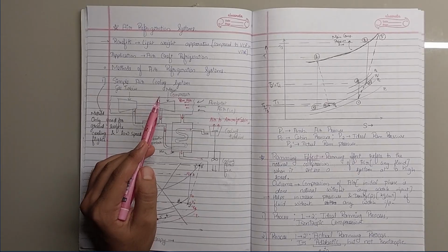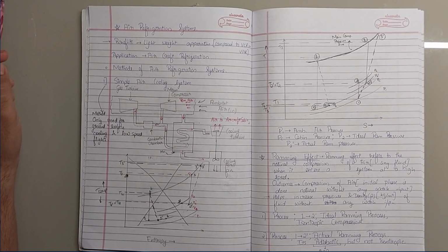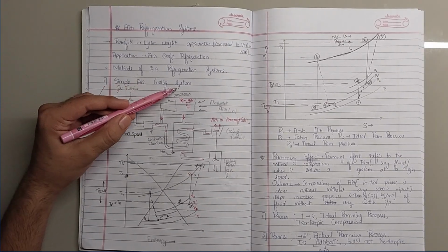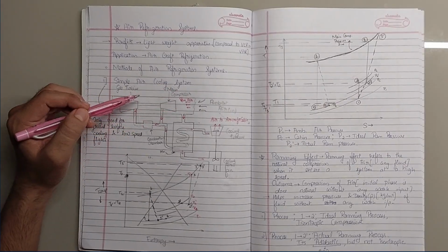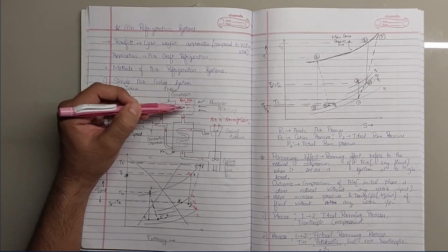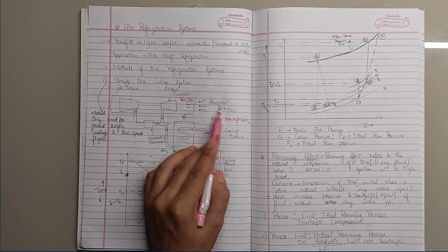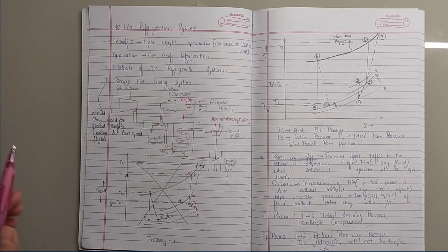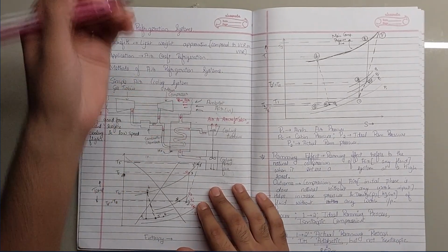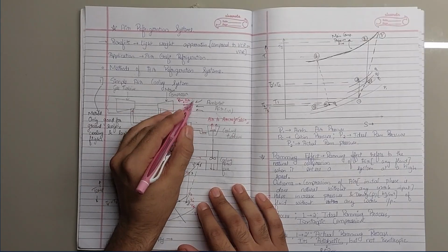An airplane flying at approximately 35,000 feet will always have very low pressure air. We need to first compress it to a high pressure. But using an auxiliary compressor will increase the work done and will eventually decrease the COP. Hence, we have small openings in the aircraft wings wherein the atmospheric air rushes in. An aircraft on average flies at some 800 kilometers per hour, and the air moving opposite to it is at the very same speed, so it will pass through and undergo the ramming effect.